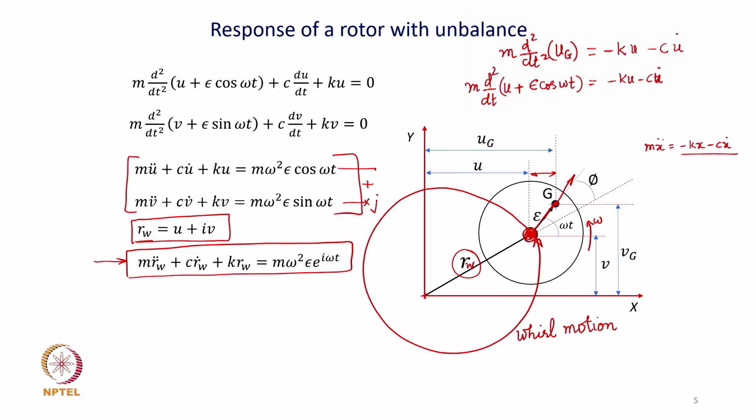But when the stretched shaft orbits around the bearing axis, that whirl motion is the vibration. Combined vertical and horizontal vibrations together trace out a whirl orbit about the bearing axis, which is here. Is that clear?